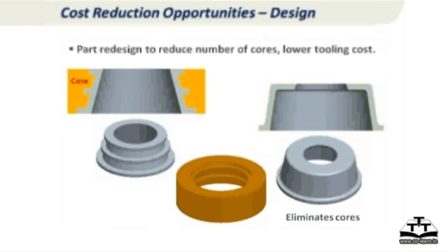Here, because those side ribs are there, you need a complicated core, which is not complicated, but it's a big core which goes all around the casting. And that can be pretty expensive because you need a big core box to make that big core, and then handling of the core, and then placing it and all that. If only you remove the ribs by some method, or you can even put them inside if you want. Anyway, I need an inside core. I can combine both into a single feature there.